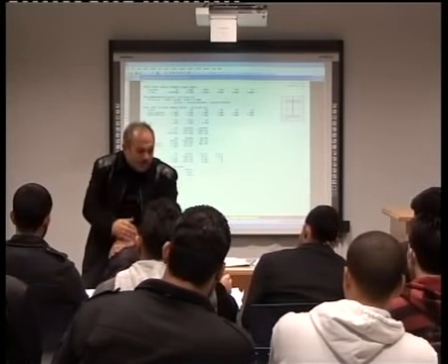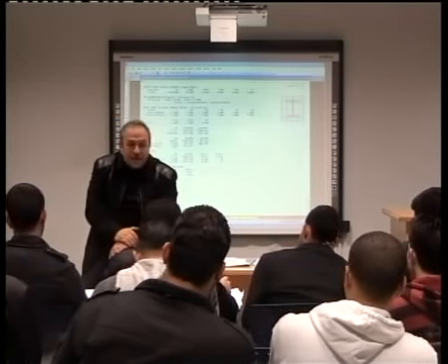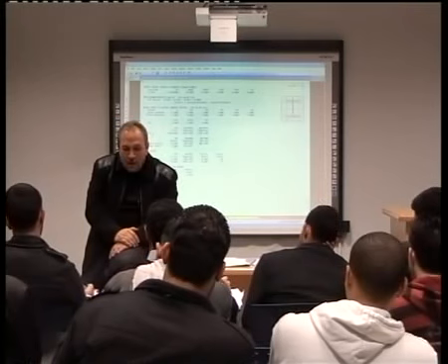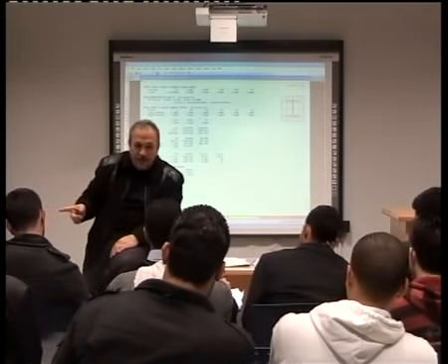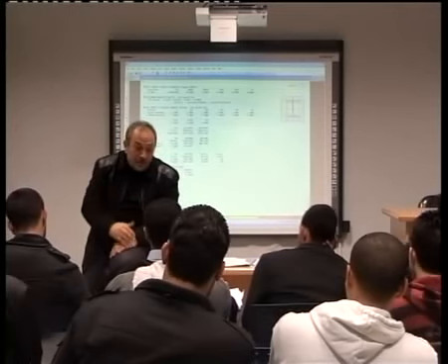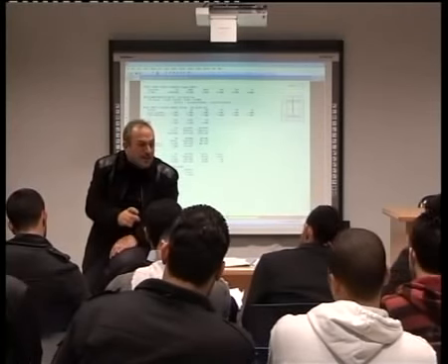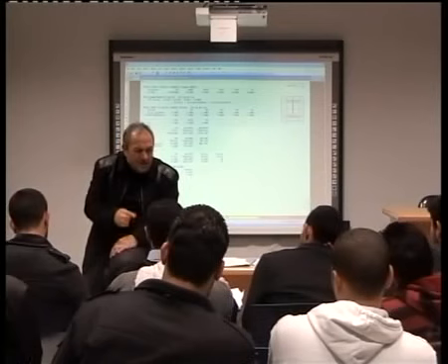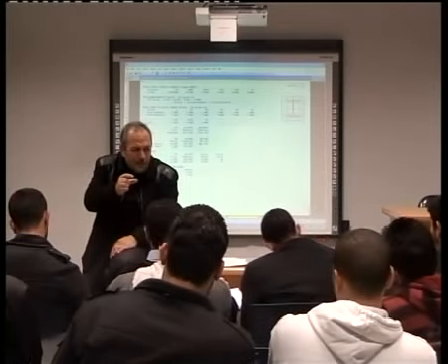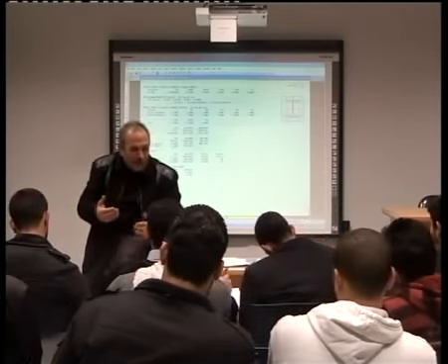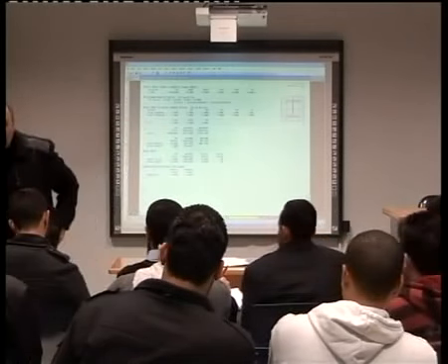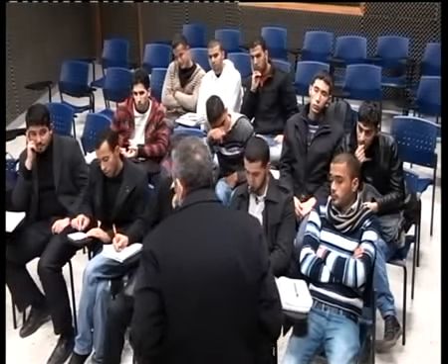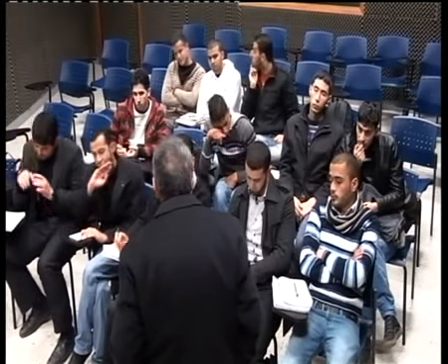So when he tells you, let us make it 10 centimeter, you find how far our feeling in practice is from where it should be. If a student tells me, let us make it 20 centimeter, I need only to remind him about the rule of L/8 so that he will draw it down, and he said, no, it doesn't work. We should go into L/7 and larger. But when you hear it from an engineer,